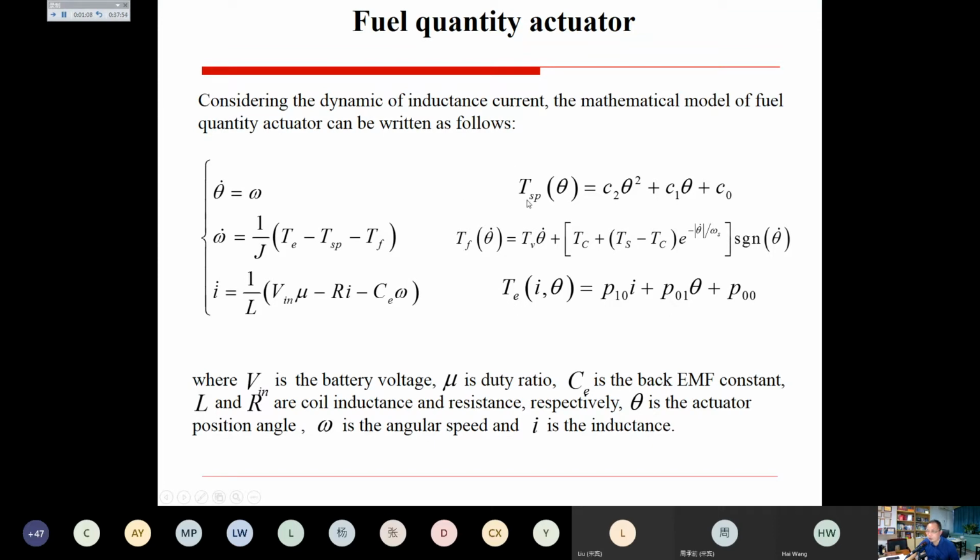Then, if you don't model it as a nonlinear model, even with a very good linear feedback, I believe the performance is not good enough because these nonlinearities exist in the system. If you just model them as a linear one, then we have a big modeling error inside the system equation, right? So they will influence the performance. Even if you use the best linear control method and the best control parameters, it will not work well because the nonlinearity exists there, right?